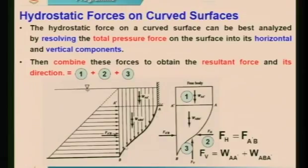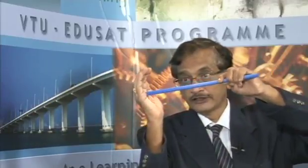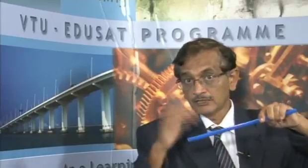Similarly, in the case of a curved surface, it will have two components. One is the horizontal component, which is totally governed by the hydrostatic force, acting like this or maybe like this, whatever it is. It means if this is holding water, my palm, one component will be like this, and the other component will be the weight of the water.